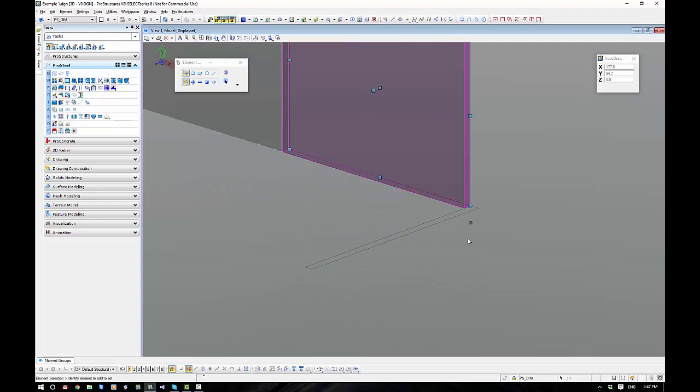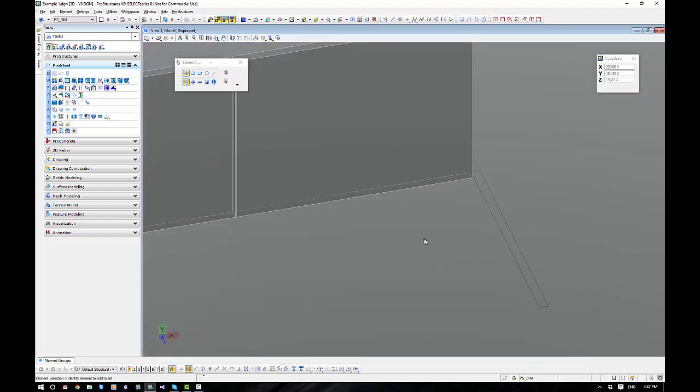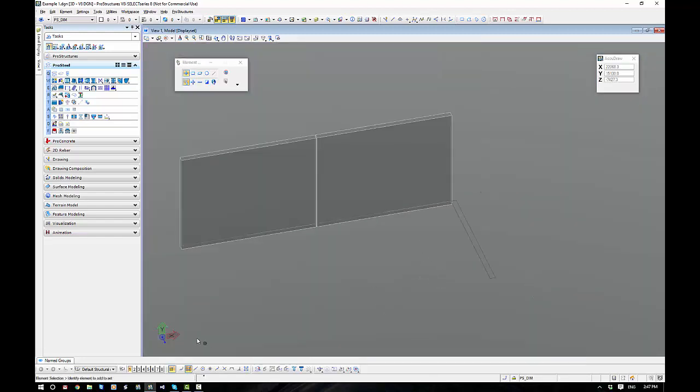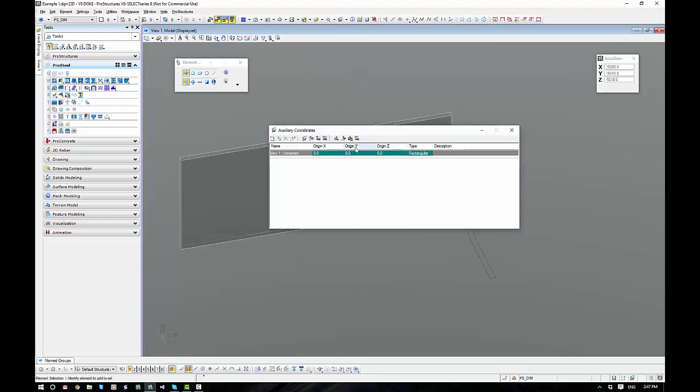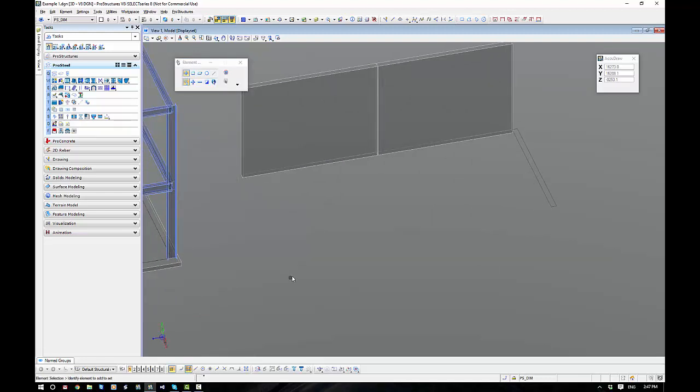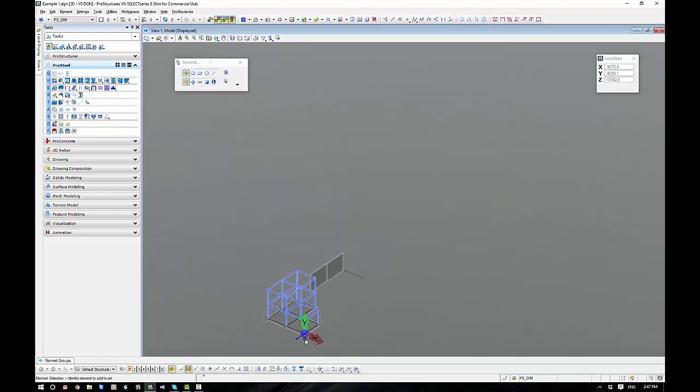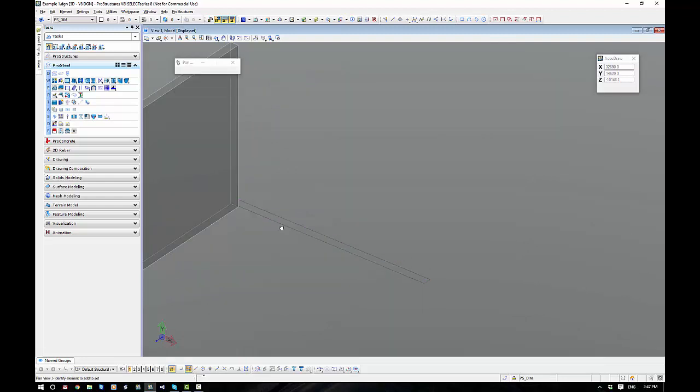In this instance, everything is all the same. Once you've got to change a direction, though, don't forget we've got to move this ACS and spin it around so that we're inside the building looking out. So in this instance, I want to spin it not on the X, but on the Y, and I want to spin it clockwise, so it'll be minus 90 degrees. Click in the model space, and you can see it spins it around. Let's have a look at that. That shows it right there. So we're technically inside looking out now, and that's how we want to draw our panels.